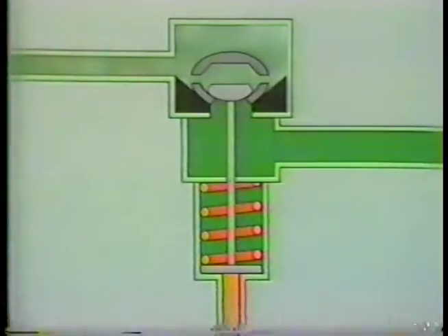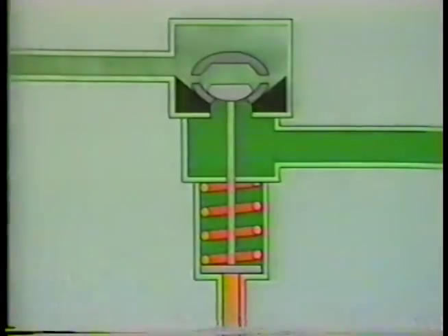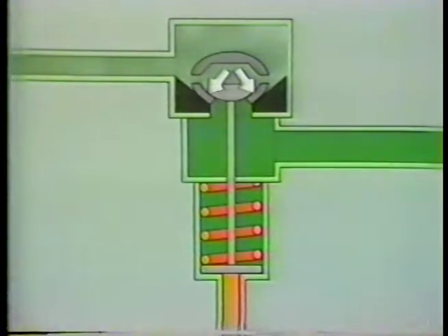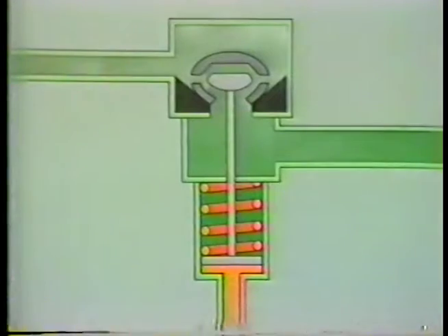The valve in this illustration is similar to the one we saw earlier, except it has an internal bypass valve. The internal bypass valve consists of a valve disc and a valve seat. Also, holes are drilled in the main stop valve disc. As the valve stem is moved toward the open position, the bypass valve is lifted off its seat. This allows a small amount of steam to flow through the holes in the main stop valve disc.